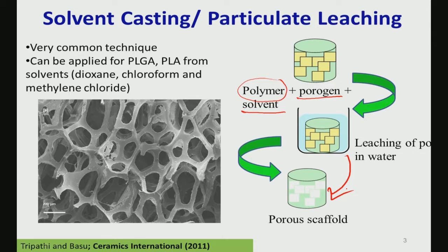This is a typical example of a porous scaffold made of hydroxyapatite. This is from our own research. As you can see, the pores that are forming here are of different sizes. If you look at cancellous bone, which is highly porous, the pore morphology is also not uniformly identical; there is a distribution of pore size and pore shape in the scaffold, and that is very typical of any biological origin material like cancellous bone, for example.